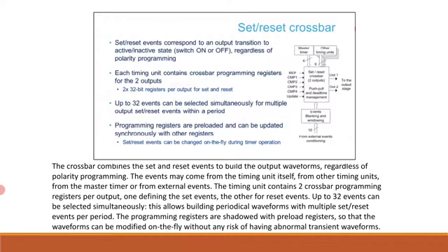The capture triggers can be selected from among 28 sources: external events, adjacent timing units, adjacent output waveforms, as well as update and software events. It is possible to simultaneously enable several trigger sources, which is a boon for any project.